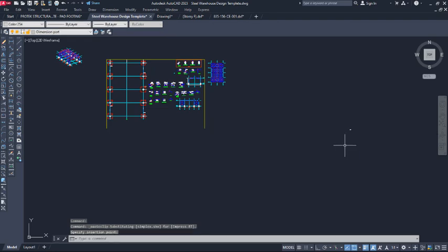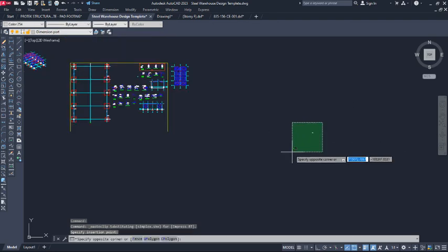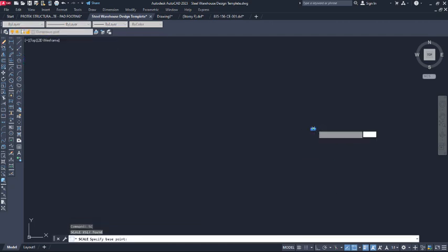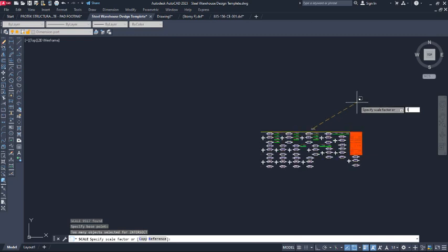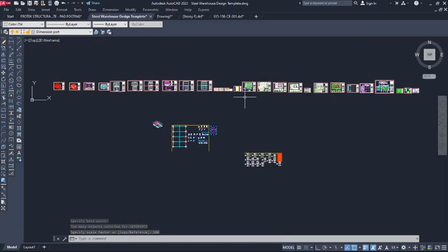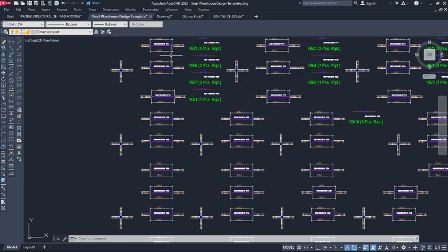So pasting it, you can see how small it is, just as I've told you earlier. I like this scale. SC on the keyboard, enter, and then pick on these drawings, move your hand this way and key in 100 so that you can meet up with the existing scale of this drawing environment. Click on the enter option there. So this is now on the same scale with these other ones, so you can easily arrange and edit all of this successfully.